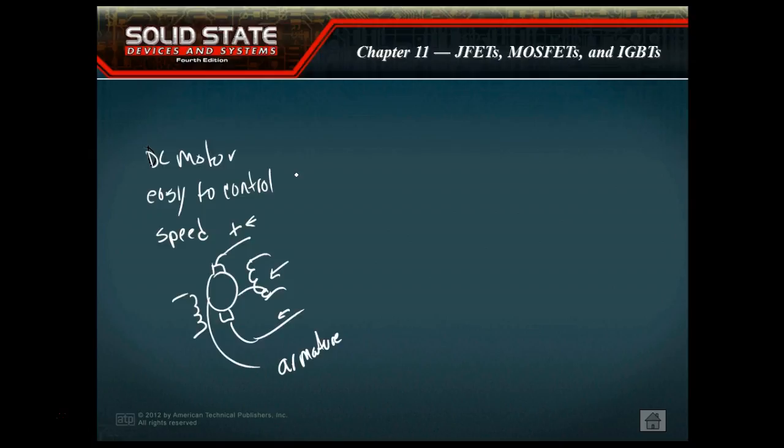Using the SCR drive, we can control them with bipolar transistors. I think I showed y'all the other night, we can control them with pulse width modulation, where we have a digital pulse that we put out to it. And then what we do is we change what we call the duty cycle. The smaller the duty cycle, the slower the motor runs. Very easy to control this.